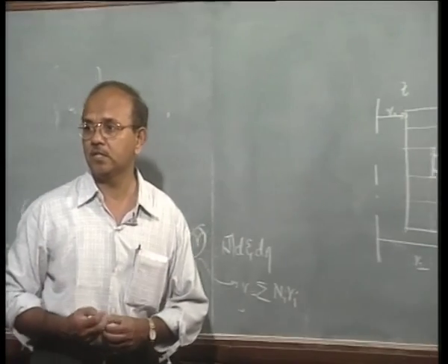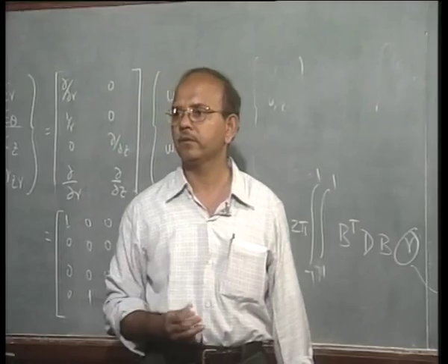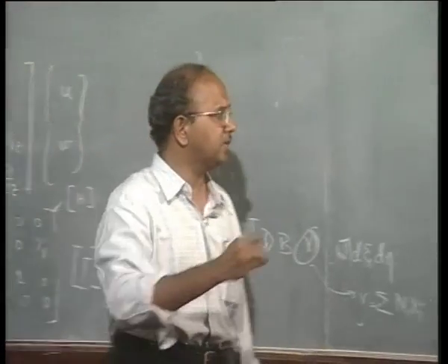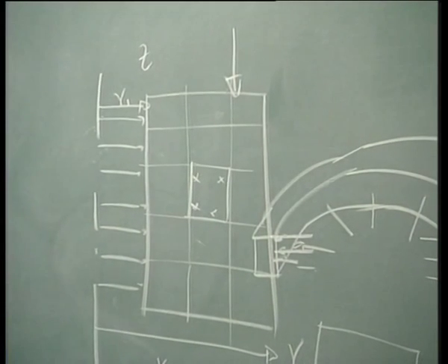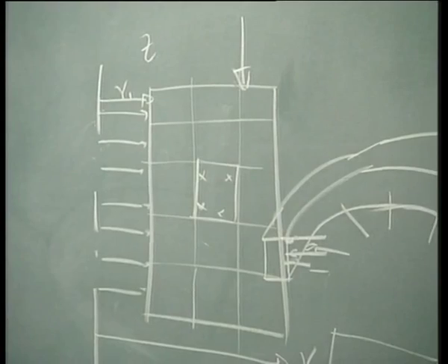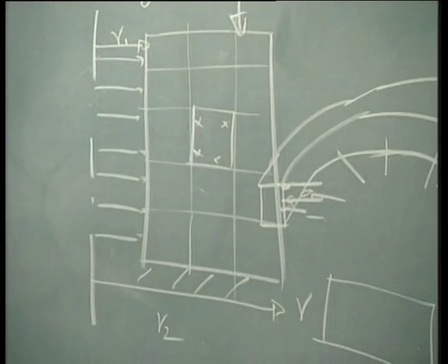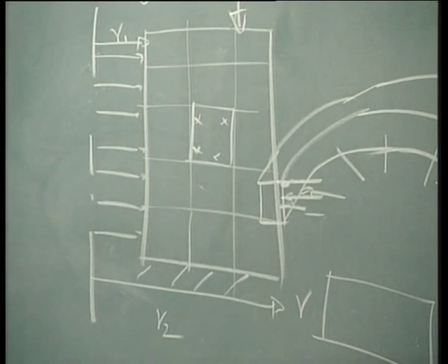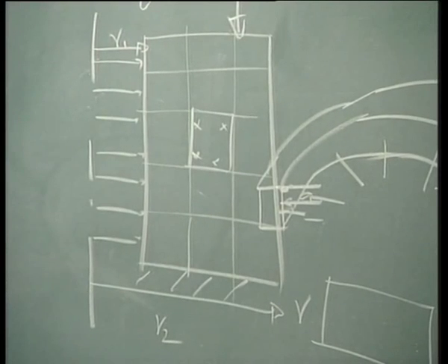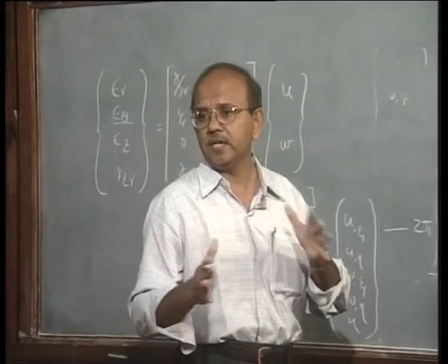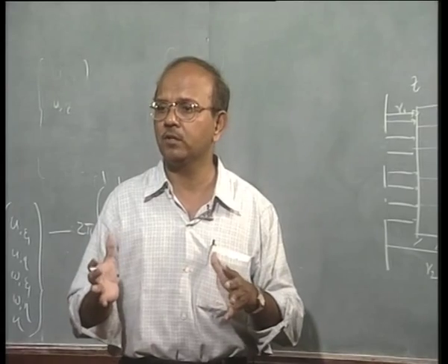okay. So in other words, suppose I have a problem where I have this particular tube, a hollow cylinder with internal pressures defined, okay. No doubt I have to specify a boundary condition in the Z direction, but I need not specify a boundary condition in the R direction, because the pressure when I integrate it would automatically equilibrate one side and the other side accurately. The formulation will take care of the rigid body motion in the R direction.